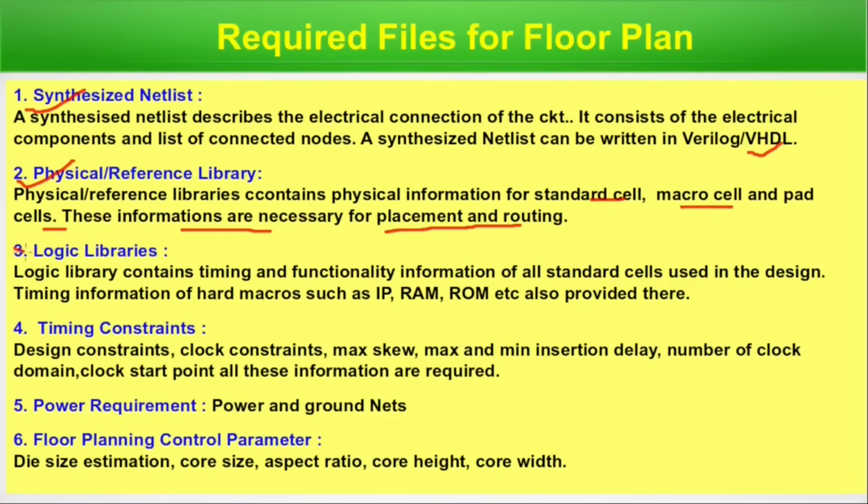Now logic libraries. A logic library contains timing and functionality information of all standard cells used in the design. Timing information of hard macros such as IP, RAM, ROM, etc. is also provided here. Timing constraint, design constraint, clock constraint, max and min insertion delay, number of clock domains, clock start point, all this information is required.